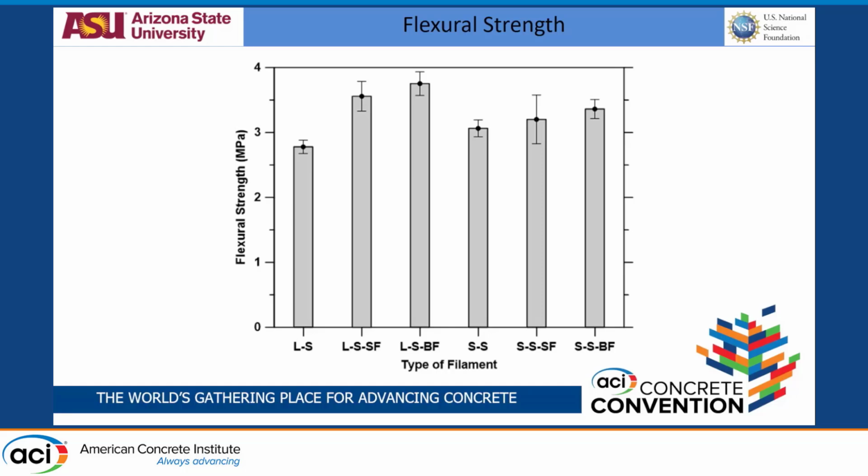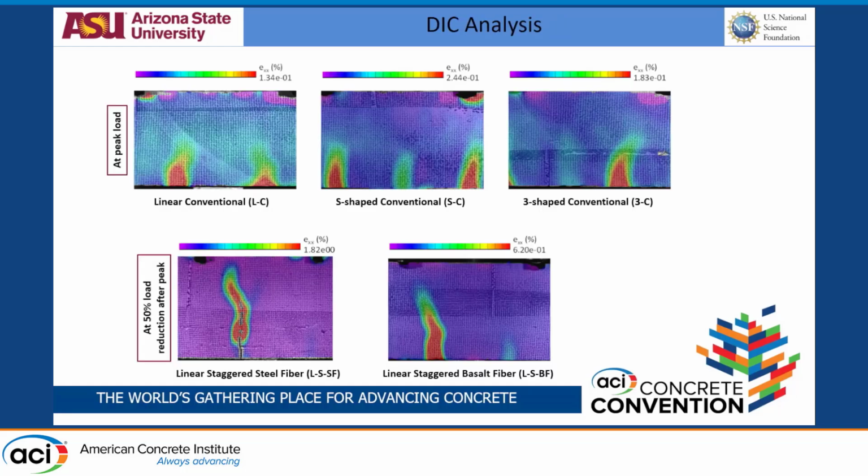But when you incorporate fiber, now comes a question of fiber alignment. Because for our S, as I said, we took the beam span length along the print direction. Now the S does not align along the length direction except at two points, so most of the fibers are not aligned along the direction of the beam. While for the linear print, the fibers are aligned along the length of the beam. So you get more fiber output out of a linear print than the S print. Now it becomes a question of whether you want that fiber output or not. Technically, we would want it, right?